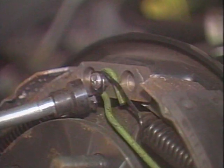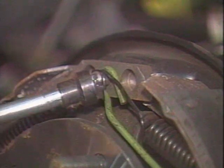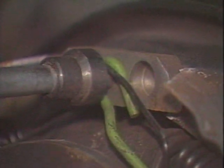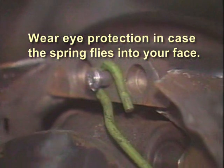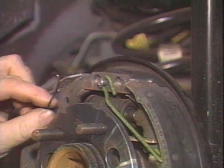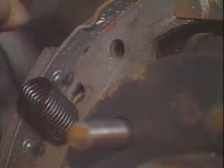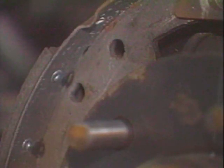To continue disassembly, use a brake spring tool to remove the upper shoe return springs. Fit the tool over the anchor pin and turn. This will force the upper end of the spring off of the pin. Wear eye protection in case the spring flies into your face. Organize the springs so that they can be installed in the same locations. The primary and secondary springs are usually a different color and tension.